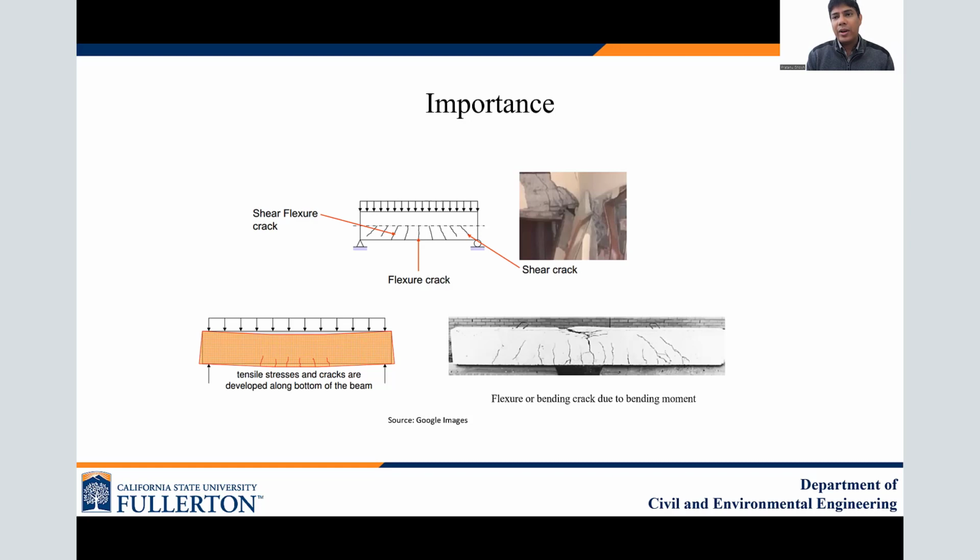As the load increases, after a certain amount of time, you can see that the beam will develop some amount of cracking from the corner as well as in the middle. The corner cracking develops due to shear, and most of the cracking in the middle develops due to flexure or bending moment, while some cracking may be a combination of shear and bending together. The most important part is to know how much shear force and bending moment develop at each location in the structural member, so that we can compare the capacity of the beam with the development of shear force and bending moment.